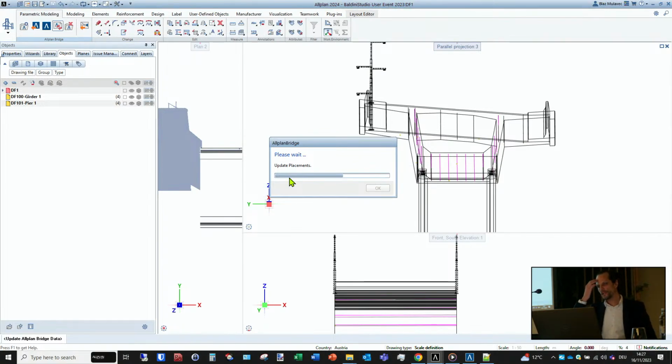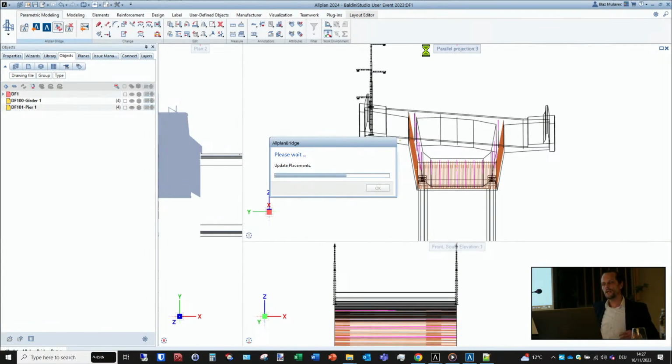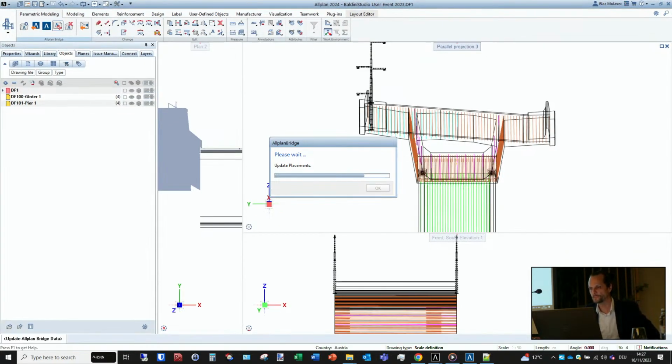And yes, I forgot to mention, for example, you see here now also bearings and street lamps at the top. These are also Python parts, which I have placed in the cross section. I will show you later. We use Python parts for such equipment, or we could also use it, for example, for steel struts at the side of our cross section. Actually, for every element which is repeating itself punctually along the axis at some specific stations, for example.